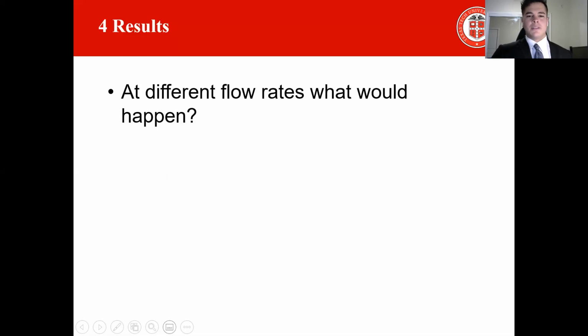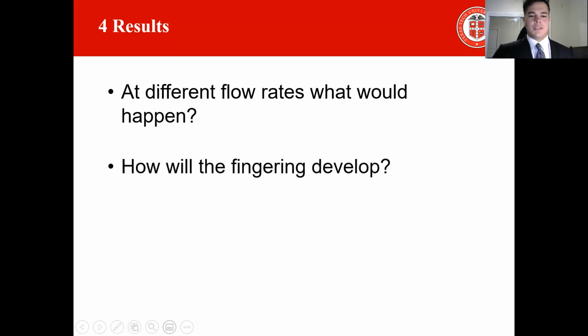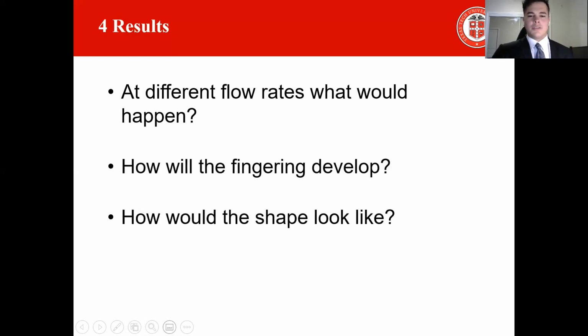The fingering pattern develops due to the viscosity ratio. In these 2 cases that we saw, we used pure glycerol. The shape of the pattern tends to look just like fingers. In many cases, all look very similar while using different experimental techniques. Overall, we can study the development of these finger-like patterns to find better ways to control viscous fingering and to enhance oil recovery.